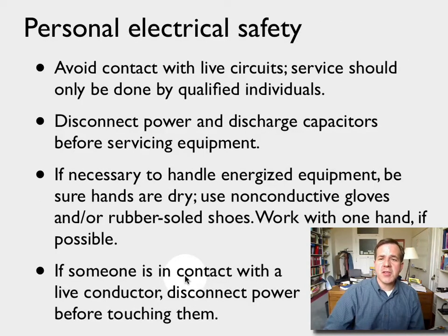With regard to personal electrical safety, of course, it goes without saying that we avoid contact with live electrical circuits. Service, if it's necessary on a live circuit, should only be done by qualified individuals. Whenever possible, of course, power should be disconnected before servicing any sort of equipment. And it's also important to note that many pieces of equipment have capacitors internally that can store significant amounts of charge well after the equipment is turned off or disconnected from power. So you need to be aware of that.